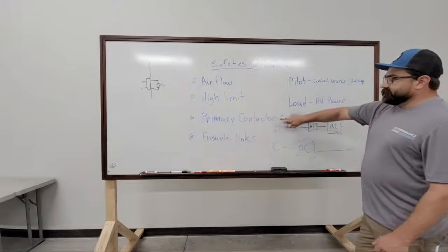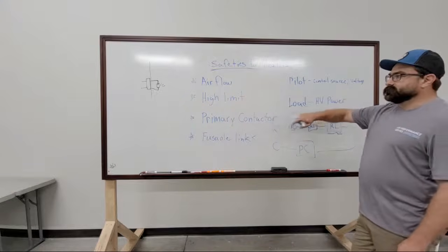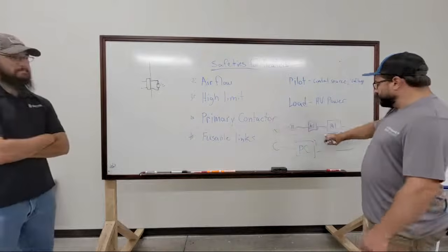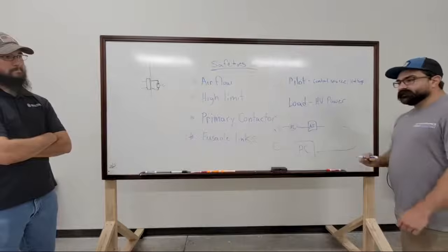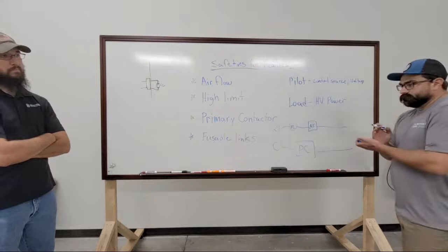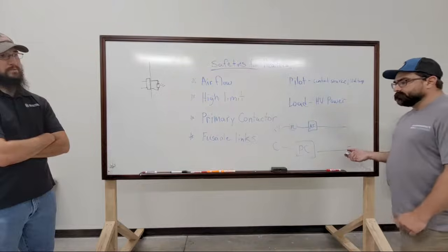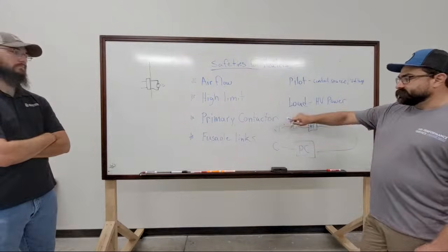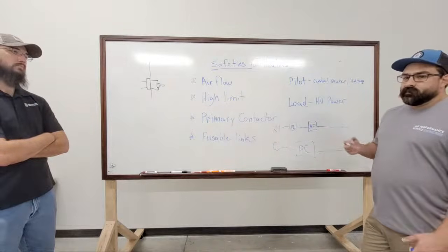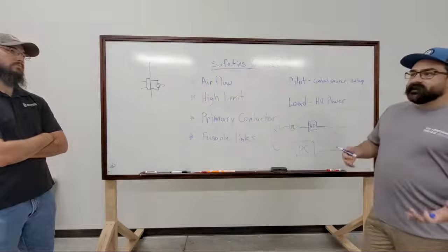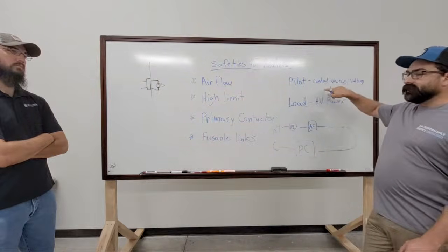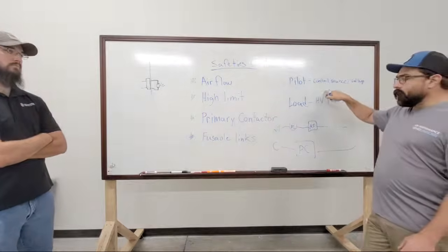When I was saying that these throw people off, a lot of times on fan power boxes, all it takes to make this guy come on are these two things. You don't need your actual heat relay to be engaged. Your heat relay or SCR, whatever it may be, does not need to be engaged. As soon as you have airflow, that primary contactor will engage. And people freak out and they're like, well, why is my heater on? It's not supposed to be on. They don't realize that there's an SCR or a pilot relay going to another contactor.